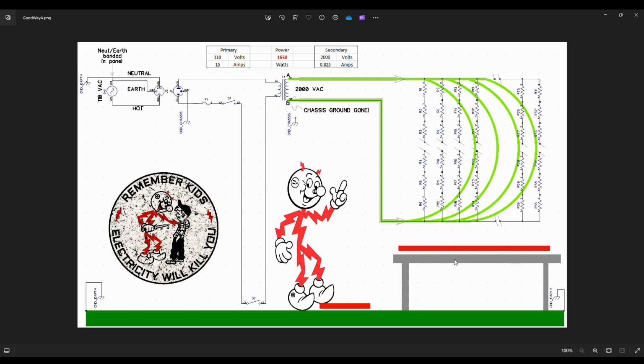There are people out there that have burned holes in their tabletop because of the way their Lichtenberg device is built on a board, and there's a screw holding the transformer down that goes almost through the board, and that board of their Lichtenberg device is sitting on this wooden table. So they've got a current pathway that comes down out of their workpiece into the table, back up through the table to terminal B, because they've got this whole apparatus sitting on the table.